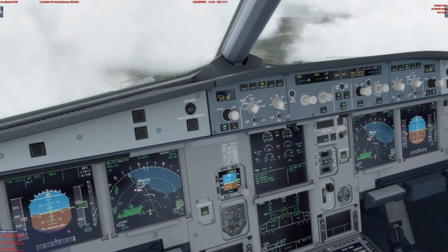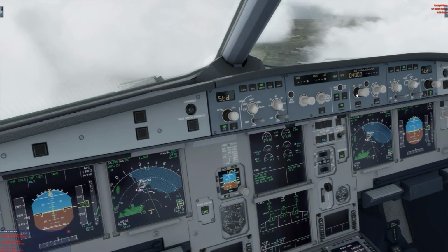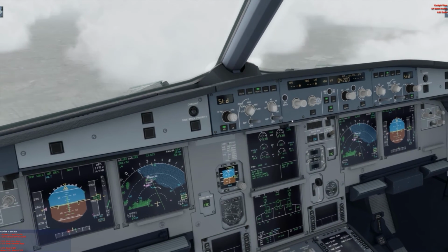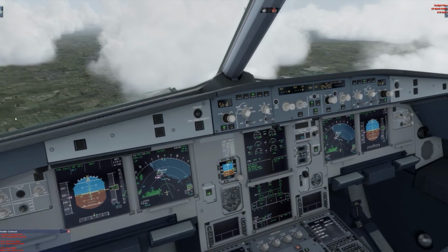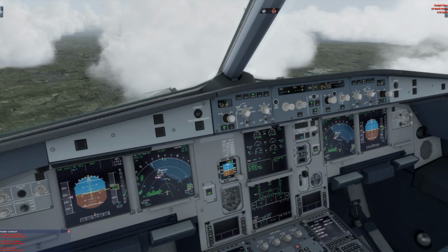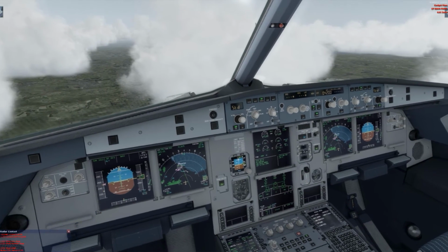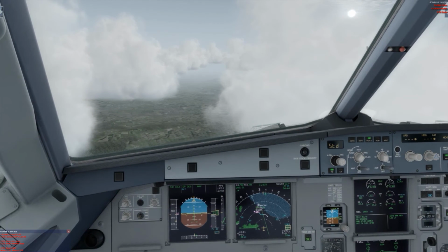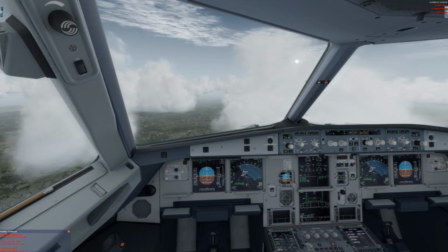Setting altitude 4,200. Altitude 4,200 set. Open descent set. Okay, left all the way back to land boards, leave on heading of 270, speed 210, Speedbird 59 Lima Lima. Looking for alt star, then down to 2,000.